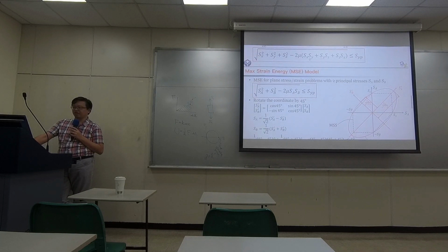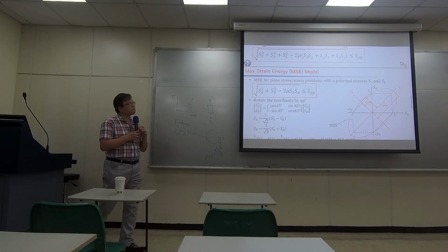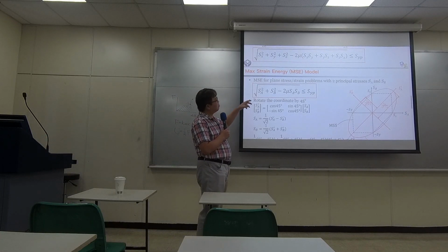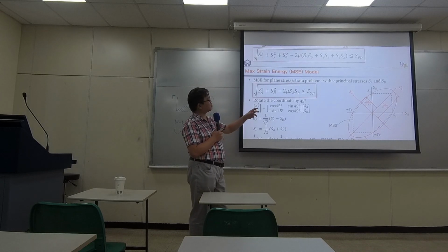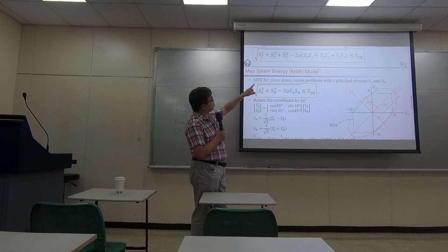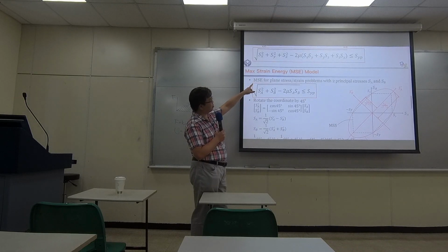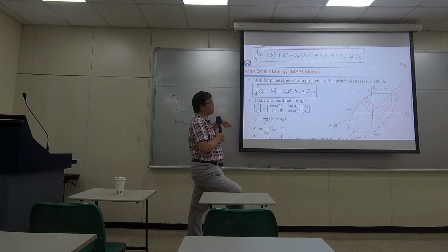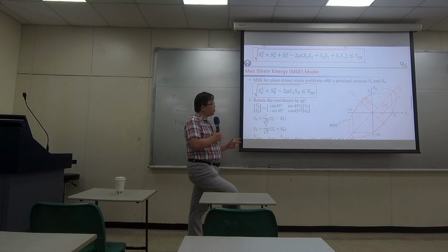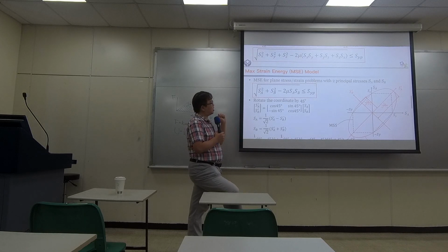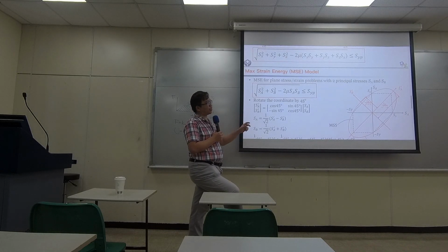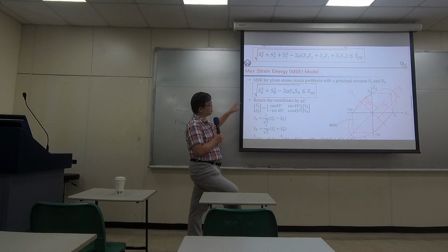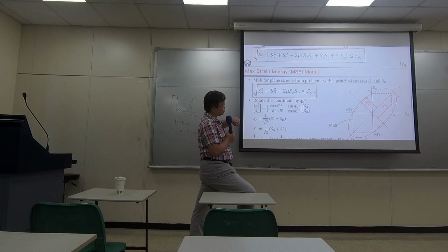Basically the same equation that we had earlier in the previous slide. What happened was, because we are only talking about a plane stress or plane strain problem, there is no stress in the third direction. So Sz equals 0. And I just converted x and y to A and B. Like I said earlier, A and B don't need to be principal stresses along any direction. Basically, they are the two principal stresses on the plane.